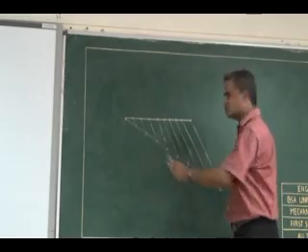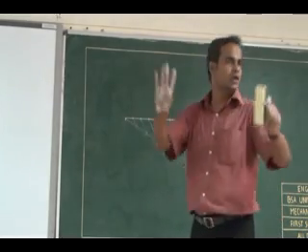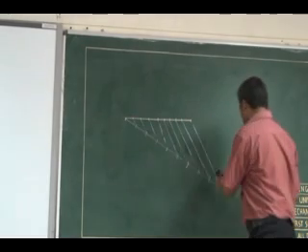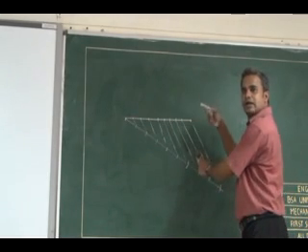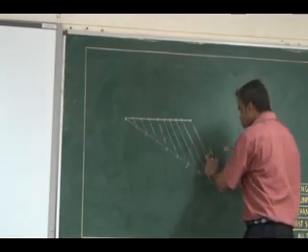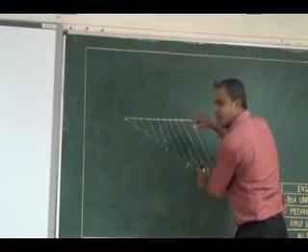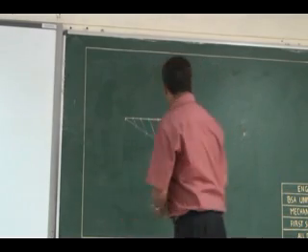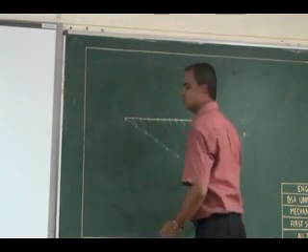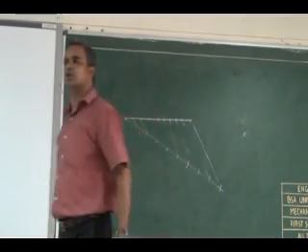Okay, the white lines are 2H, these are all construction, it should not be visible in your drawing sheet, right? It should be very light. So the extreme line I can connect it with my drafter and fix your drafter to that. To move your drafter just parallel to this location, wherever it intersects, that location alone we mark it. I can avoid these constructions. Okay, that location alone we mark.